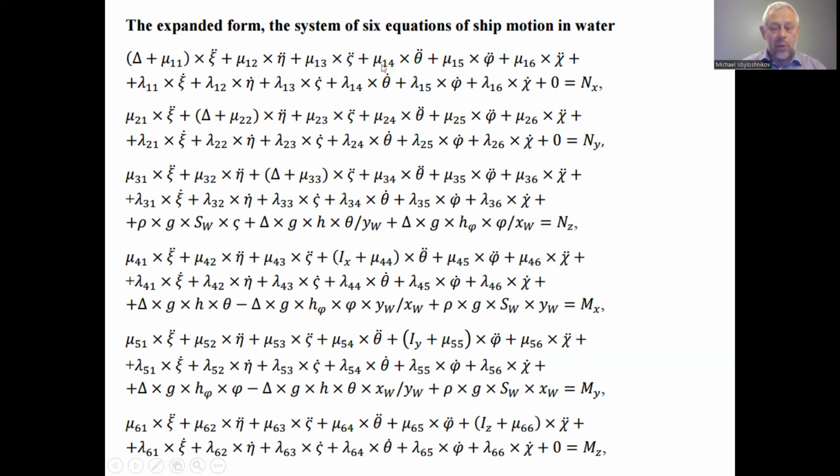And this is the force of inertia arising along the abscissa axis under the action of the acceleration phi theta second derivative, the acceleration of the ship rolling, this acceleration of the ship pitching, this acceleration of the ship yaw. All these factors indicate that all summands respond to the inertial forces arising along the abscissa axis on behalf of all other directions of the ship motion with acceleration.